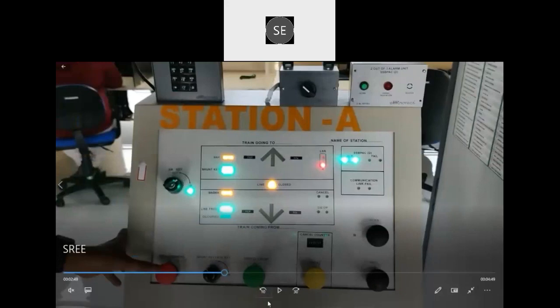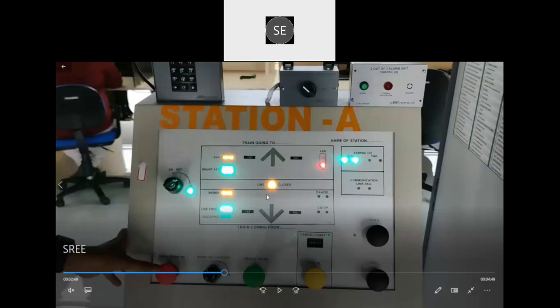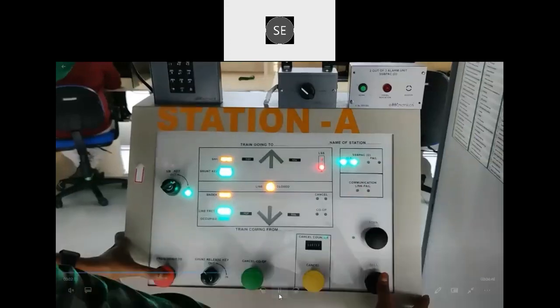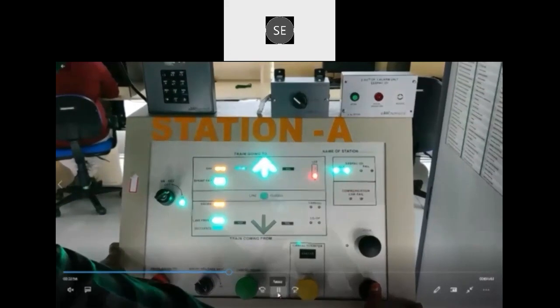We can see a number of indications here. Now the block status is line closed, indicated by this line closed indication, and the status of LSS is shown here, along with signal normal indication, shunting key indication for single line, signal normal of the other end station, and of course the axle counter status. Now SSBPAC is okay, so it is glowing green. TGT and bell buttons are pressed for line clear. So now we have received line clear.